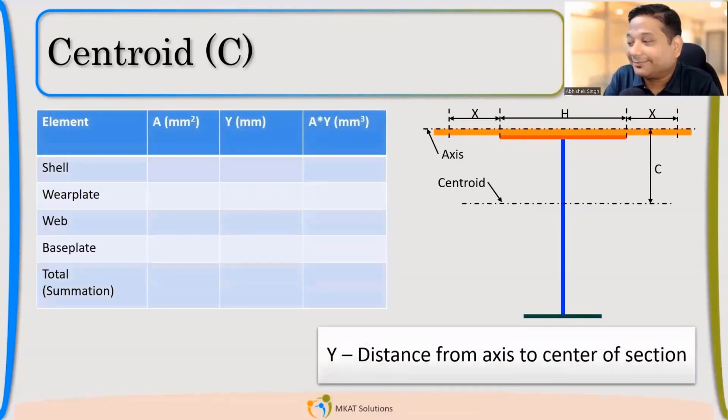What do we call it? Decay length. Yeah. You can call it stiffening length, but that is not exact; it will be very subjective to that part. For the stiffening ring also we calculate something like this, right? And the exact formula is there. It's basically 1.1 under root Dt. But if you write the D in R terms, you will get again 1.56 under root RT. Okay. So if you remember, when we calculate the stiffening along with the shell, we take some part of the shell, isn't it?